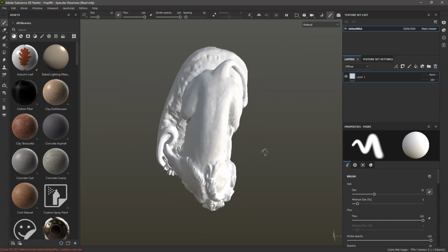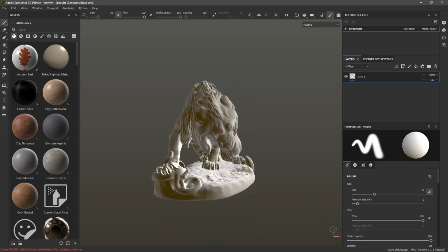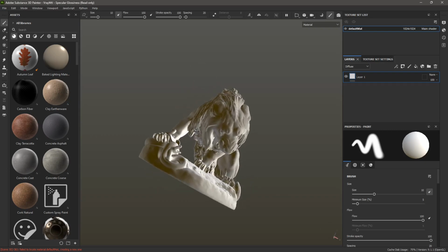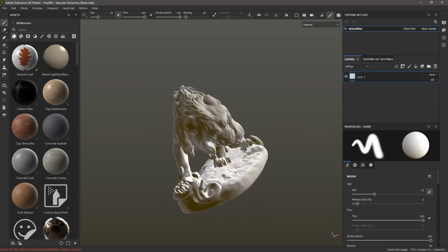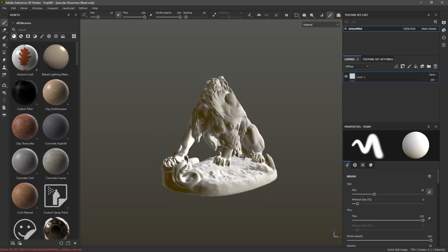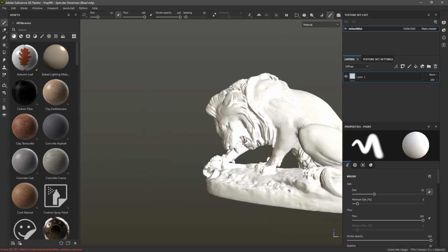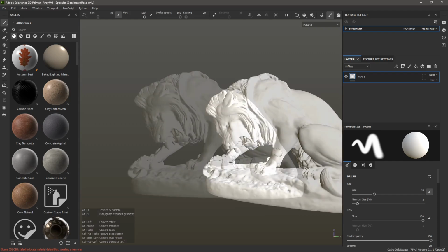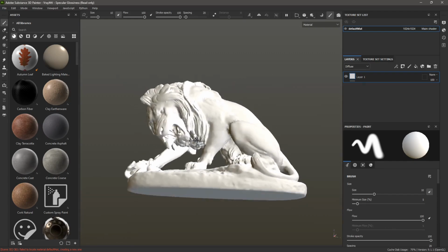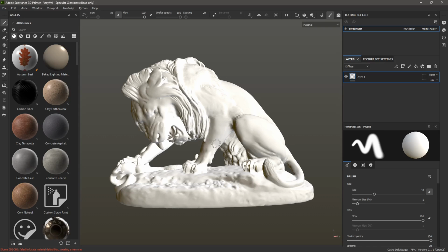And also we are seeing this from the top because, depending on where this model was created, you have different types of orientation and axis. You can see that Z right now is the height. And if I try to orbit around, it's going to orbit in a strange way. So something I can do is change this to free rotation, just rotate it like this. You can hold the Alt and the Shift key and try to find a good front view, and then I'm going to orbit a little bit like this. So that's going to be fine for what I need to do.